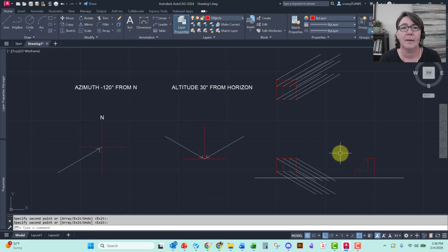So just like before, when we cast the shadow of different parts of the object, I'm going to deconstruct this. I'm going to build this back piece first, and then probably the base, and then finally add in this triangular wedge. Okay. So starting with the back piece, the shadow is going to come up, over, down, and back. How far does it go? It goes pretty far because we've got that low sun angle. So it's going to go all the way out here.